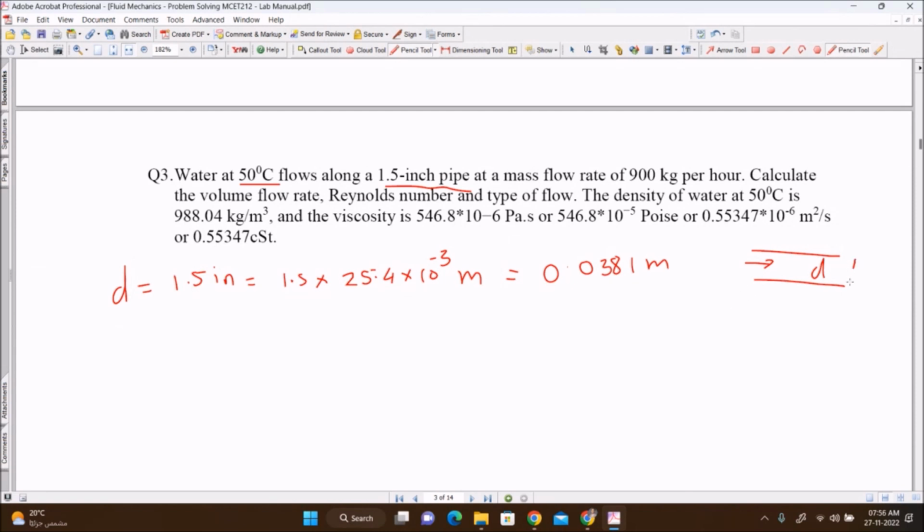So what is our target? You need to find the cross section area. Once you know the area, we can find the discharge Q. Discharge, area, this is the flow area, these are the parameters we need in fluid mechanics. So I can find the velocity V is equal to Q by A, as a continuity equation. Or mass flow rate m is equal to rho AV, and AV is nothing but discharge, so rho Q.